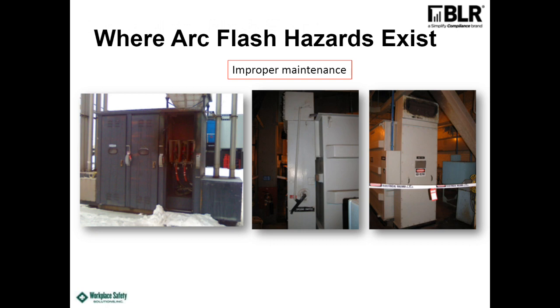The one on the left shows switchgear where there was an operation. Once it was operated, there was actually a failure inside the switchgear, and it blew the door completely off. You can see the 2 doors to the left. They're actually quite heavy doors, but it blew them right off completely. The person that was doing the switching was blown about 25 feet back and ended up in the hospital for a while, but ended up okay. So that was lack of maintenance on that one.